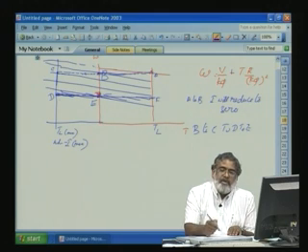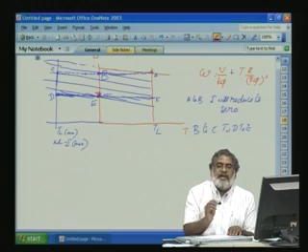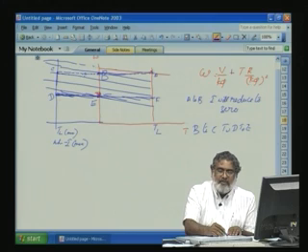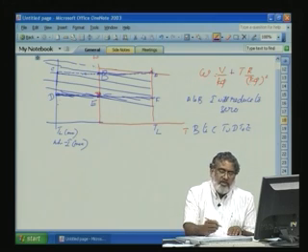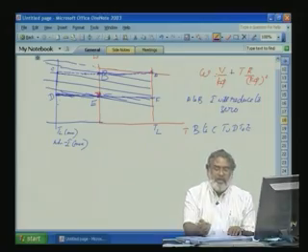We are controlling the driving current or the current from the machine so that the machine will quickly come to the stable state. So, there are electrical time constant and mechanical time constant involved. So, this we have to properly sense and control, so that the machine should come to the proper speed without any overshoot in current, and current should not go beyond the rated value. At the same time, during regeneration we should develop the maximum negative torque from the machine, so that the machine will accelerate or decelerate with the minimum time possible.